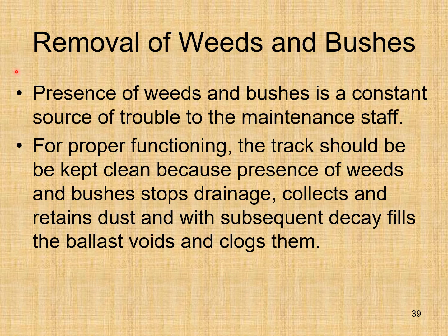Removal of weeds and bushes. Presence of weeds and bushes is a constant source of trouble to the maintenance staff or team. For proper functioning, the track should be kept clean because presence of weeds and bushes stops drainage, collects and retains dust, which by subsequent decay fills the ballast voids and clogs them.